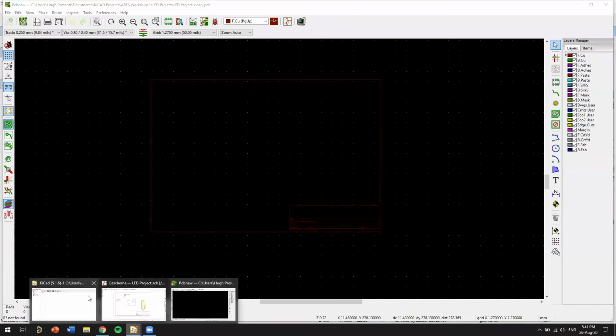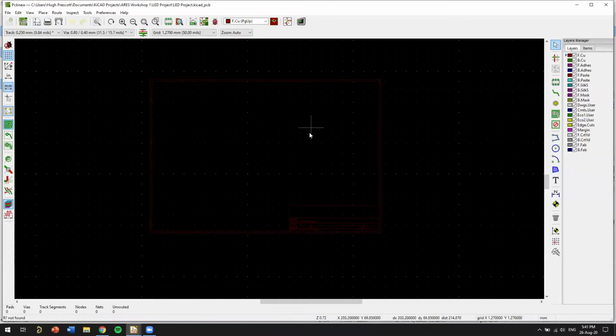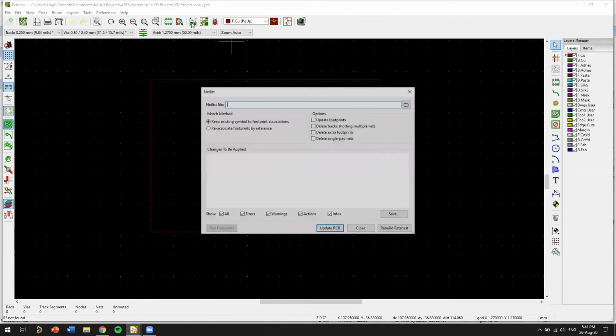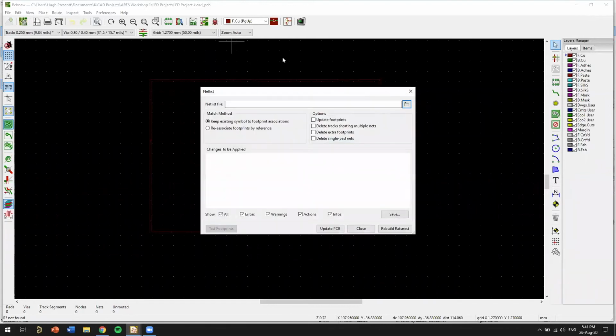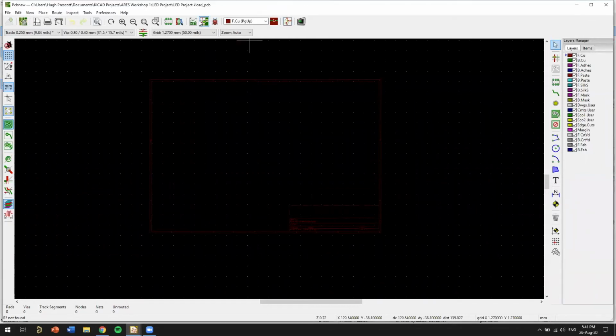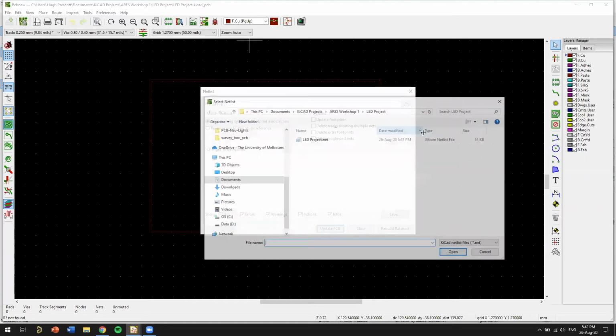We need that because we're now going to go onto our PCB. If we go into the PCB project, you can open up the file which has .KiCad PCB, and you're going to get to this screen here. And what we want to do is import our netlist that we just created. So we have load netlist here, this button, and then we want to find our netlist file, which is what we just generated.